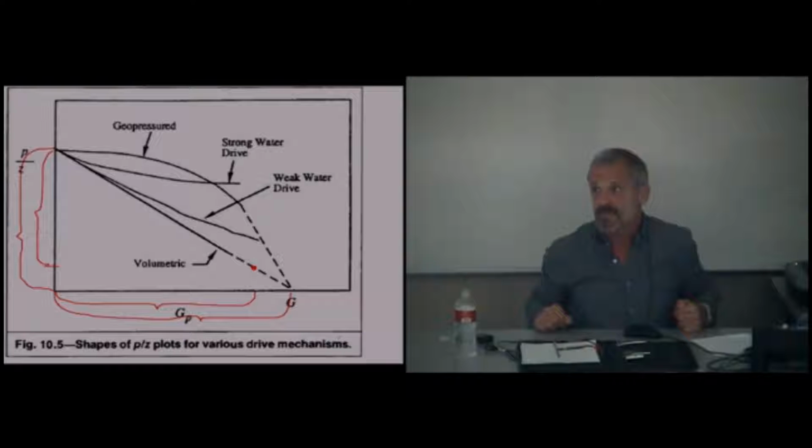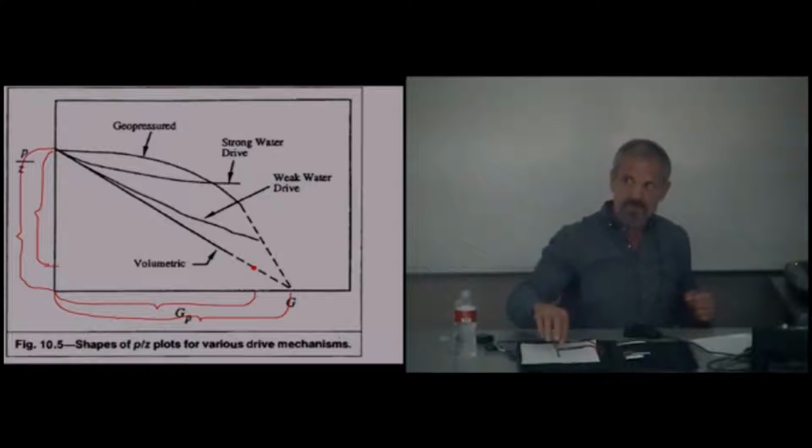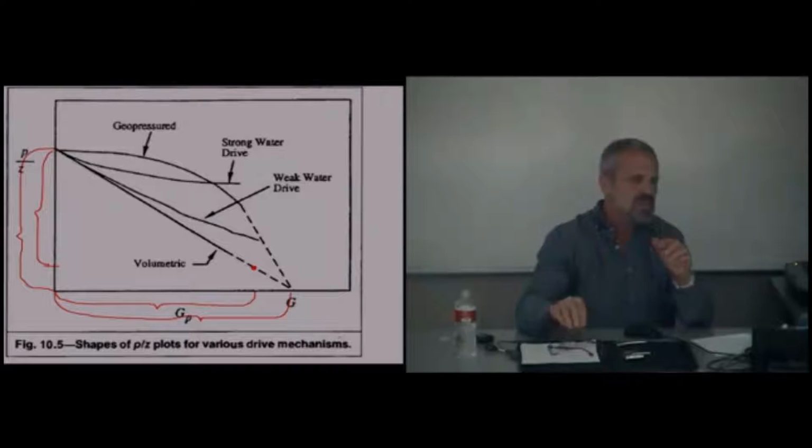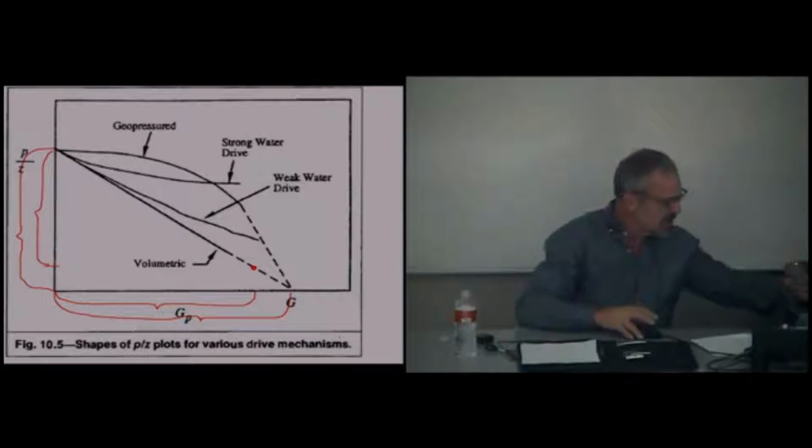Yeah. I was kind of plugging things in, and I'm just surprised that if I start plugging in values for my N2, CO2, and H2S, the recovery factor goes up as the values go up. Well, the compressibility changes. In other words, this is a good point. So he's asking why, if you add impurities, do you get a higher recovery? Let's look at that. Let me follow you along here.